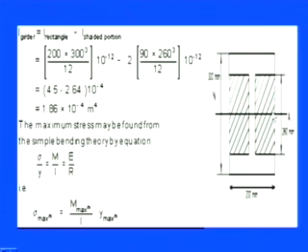So we can simply calculate the I of the girder, which is equal to I of the total rectangular part minus I of the shaded area. If you remove this shaded area, then you have the I section. For the total rectangular area we have 200 into 300 cube divided by 12, that is BD cube by 12, into 10 to the power minus 12, because the dimensions are in millimeter and we want to calculate in meters.